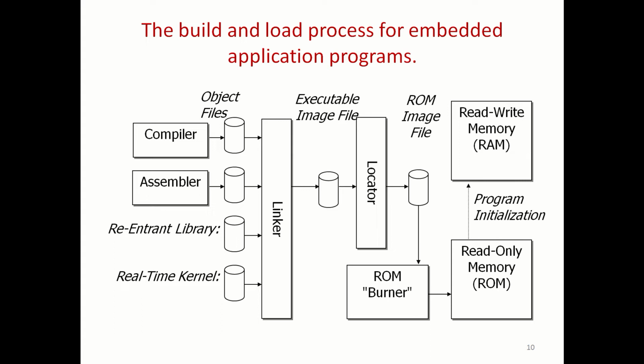Since there is no secondary storage, there is nothing like relocatable programs. I know at this stage it is slightly difficult to understand, but since I am recording my talk, at a later stage you can refer to what I am saying when you start writing the programs. So there is no relocatability here. Whatever program we are writing into the memory, everything is absolute, physical, real memory.